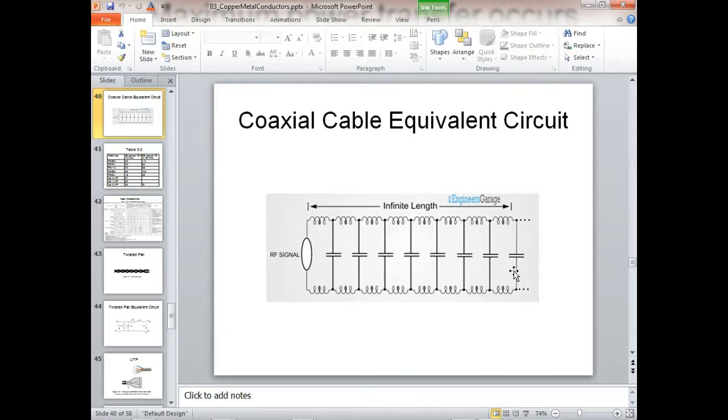The cable we used to run in networking when we first started actually running networking, we used what we call a bus topology. Basically you run one big long cable the whole length of the network, and then you just tap onto it. And it was 75 ohm cable. Well, what you'd have problems is people would go down to Walmart and buy 50 ohm cable, and they want to run a network on it. It was a 75 ohm system, and what? Wouldn't work because they screwed up the impedance matching.